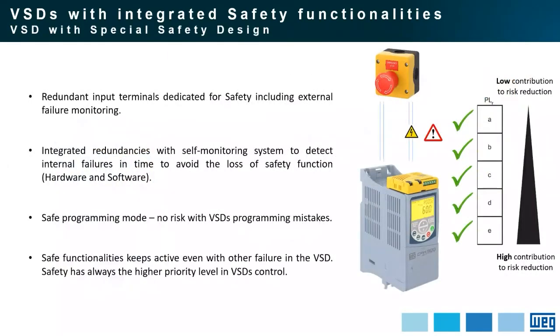But in the end, how can the variable speed drive control it in a safe way, and comply with all the safety standards? So internally, or let me start with externally, the variable speed drive has redundant input terminals dedicated for safety, including external failure monitoring.